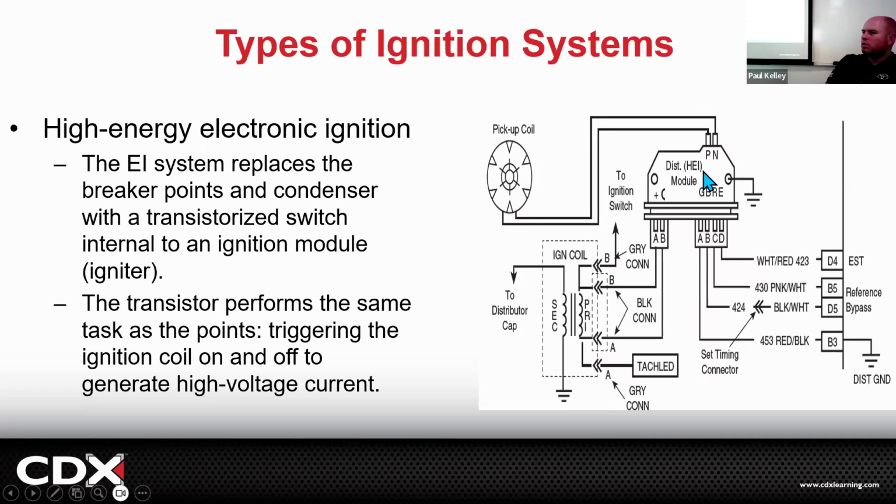You know what the ignition module would do? Well, when it wasn't close, it would do the dwell. It would charge the coil up. But when it did get close, the ignition module electronically would open up B. You see B right here? So A is giving voltage to the coil, and B is giving ground to the coil. So it would go ahead and be like, you know what, B, open it. When it opens B electronically, what happens?